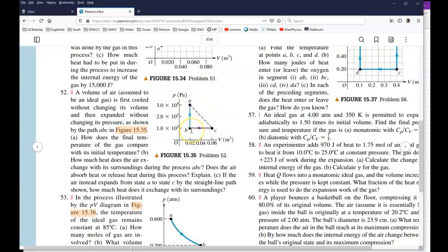So this process right here from A to B is isovolumetric, work equals 0. As you can see, there is no area under the curve there. And then from B to C, there is a work there because there is area under the curve. And that's isobaric. And isobaric equal to what? P delta V, correct? So that's basically what we have. Then he has this dotted line. I have no idea why. When we read the problem, we'll see why he put that dotted line.